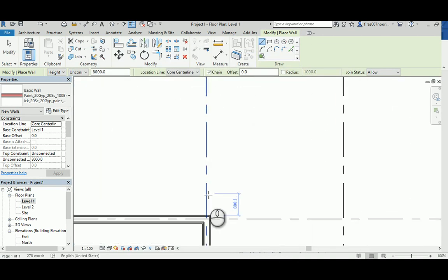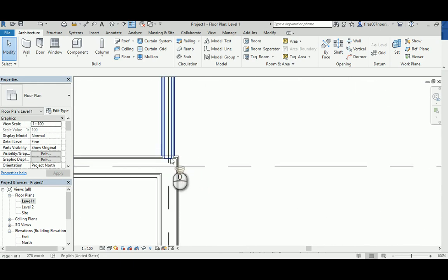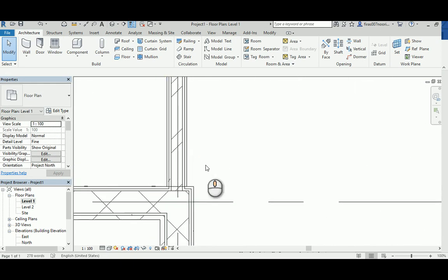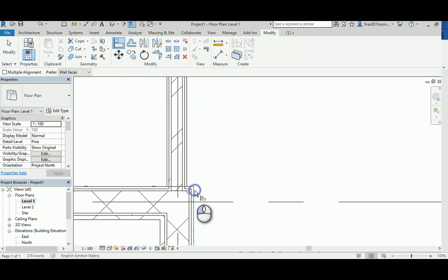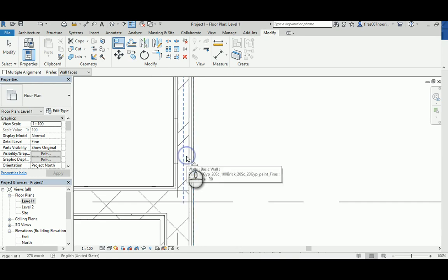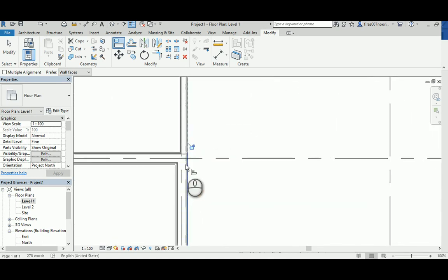Now the common issue that I notice most of the students have, again, is the core center line. That's what your hand goes with immediately. Now if you start off from here to here, and then you select, you think, oh, what have I done, what is this, an ugly business. So you say, okay, I should have picked exterior, right? Finish exterior. And then you say, okay, let me do a line, and I want this reference, and make that go with it. Notice here, now it's jumped happily. Most of the time, it's because of the joining, it shifted that guy with it.